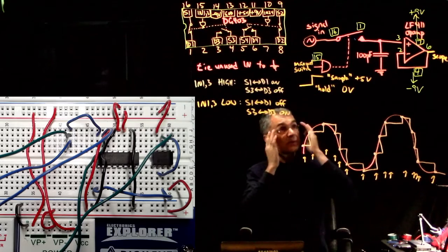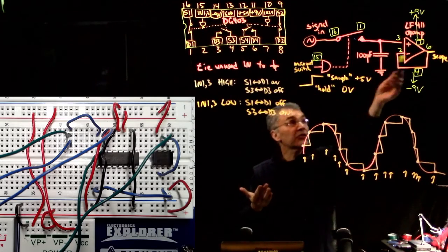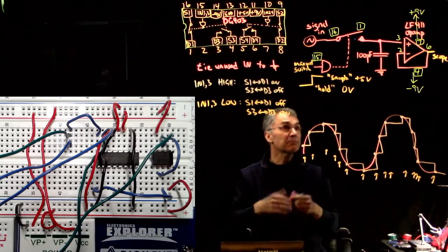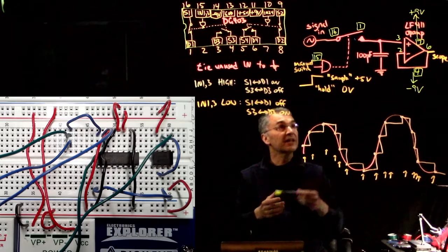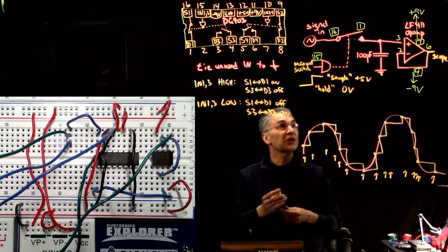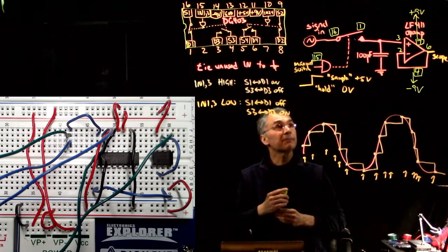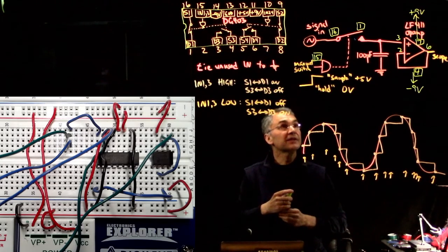And normally what you look at it with might be like an oscilloscope probe. But an oscilloscope probe is not a perfect voltage probe. It has like a 10 megaohm input resistance. And if this is only 100 picofarads capacitance, then what's the RC time constant there?